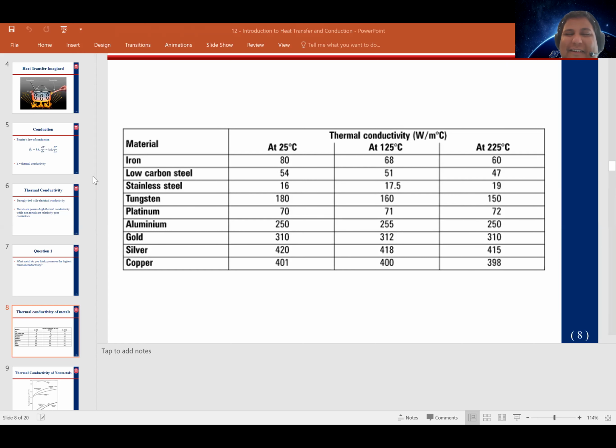I like that, Eduardo. Now, gold is advantageous in electronics primarily because gold has an extremely high corrosion resistance. And so it can outlast a lot of these metals, particularly copper and silver. Copper oxidizes fairly easily. So when placed in the wrong environment, copper suffers very quickly. You can essentially get a shell of copper oxide on the outside of your metal, rendering it useless. Silver has similar issues, though it's slightly better in terms of resistance than copper, but gold definitely outshines in terms of durability and corrosion resistance.